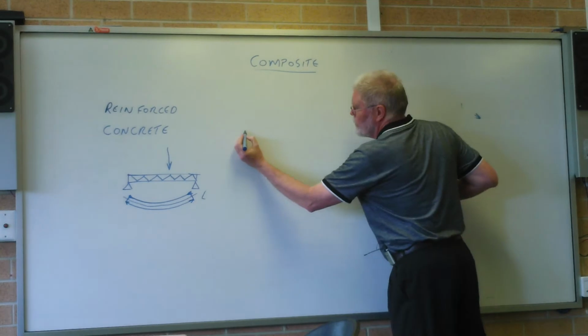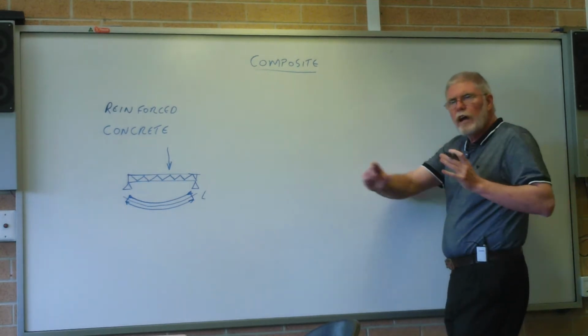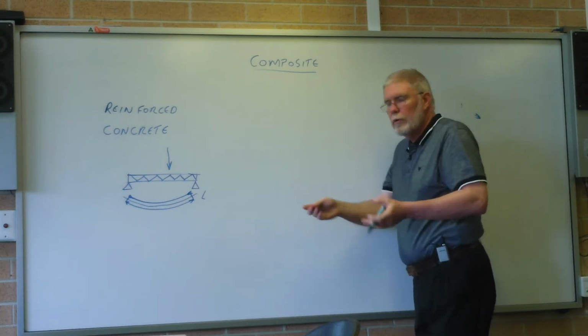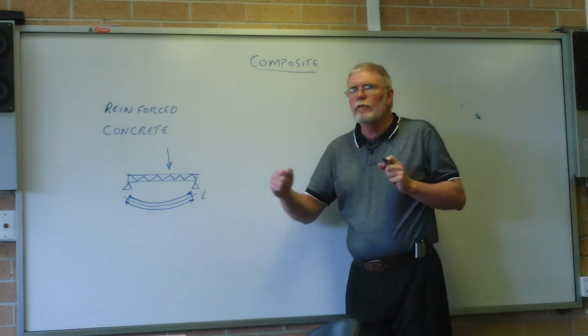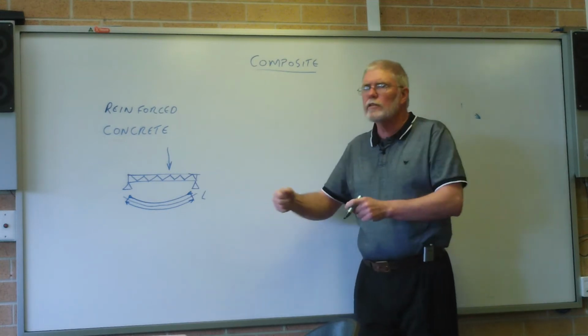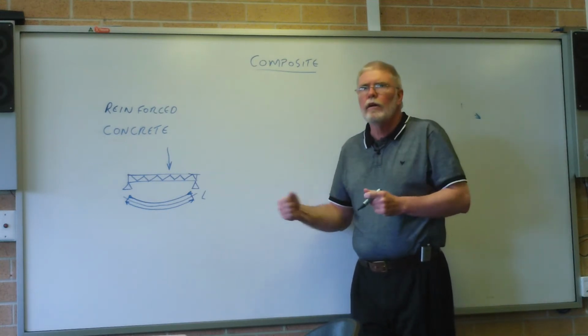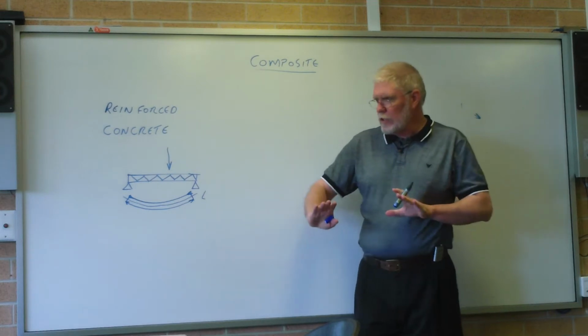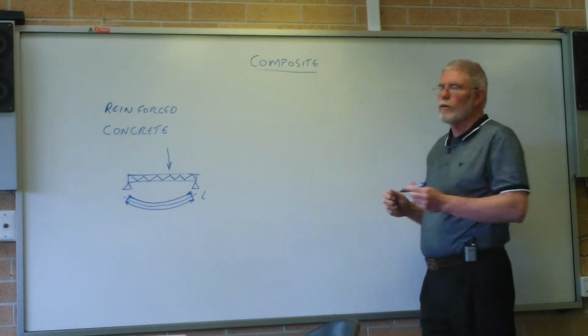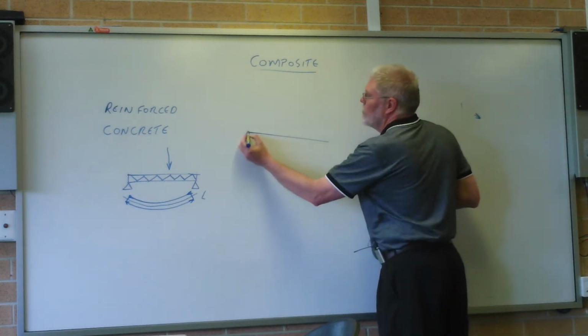So let's say we make a concrete beam. We've cast it out, we put a couple of pieces of wood down the side as formwork, we pour the concrete in, we know that if we keep it moving, we can make it all reasonable. So we bang the sides of it, pop it up and down to get the air out, that sort of stuff, agitate it, then you say, right, it's ready, leave it. So now we've got this beam of concrete we've created, a big block of concrete,